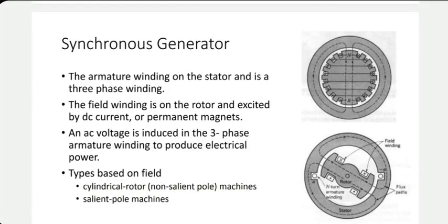Synchronous generator is the opposite of synchronous motors, and this is the one that we call alternator. I have been talking about it a lot. I'll be talking about it a lot anyway. So the essential idea is that it operates only when the rotor is at synchronous speed. I told you last time that depending on the speed of the rotor, you can have either salient pole rotor or cylindrical type of rotor. In cylindrical rotor, we use electromagnetic techniques to create magnetic poles, while for salient pole machines, we actually have physically visible poles, bolted or welded to the construction.